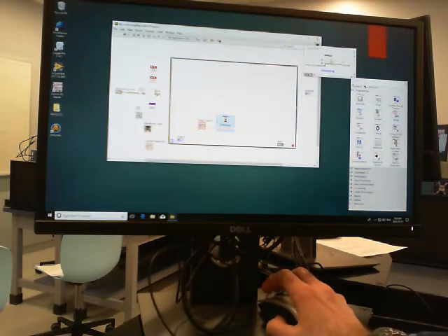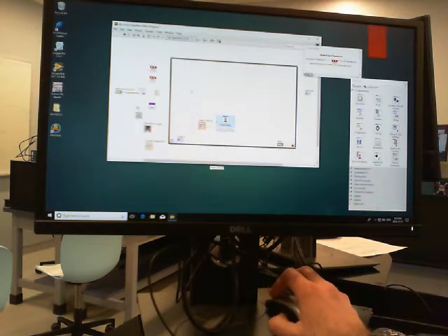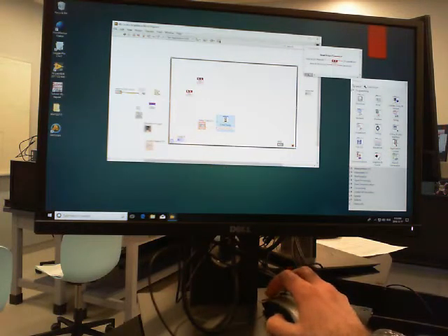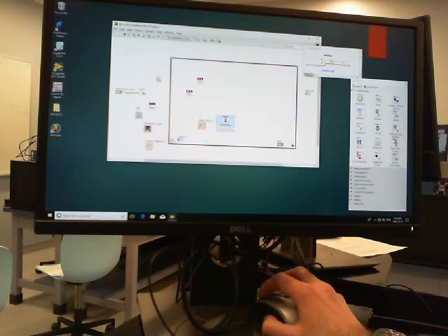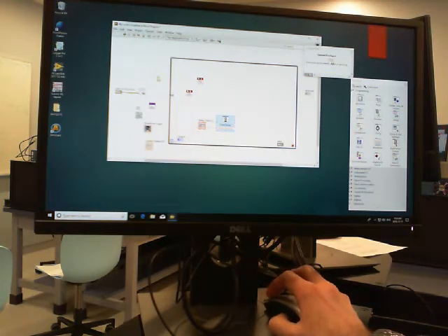And what does that mean? Well, we're going to have to read the signals from the scope. We're going to have to read our detector signal, and we're going to have to read our reference signal. And so we'll have to read those from the scope, and so we'll use this read scope sub VI, which is created for you. And of course that'll have to be inside the while loop. And we want to use the error signal to control the flow in the program, so we'll just wire up the error signal. If the first thing we want to do inside the while loop is read the scope, well, we'll read the scope. We'll wire it up to be the first thing.